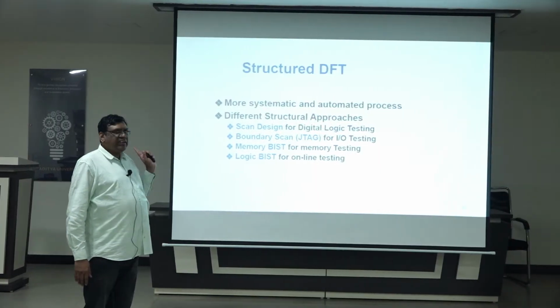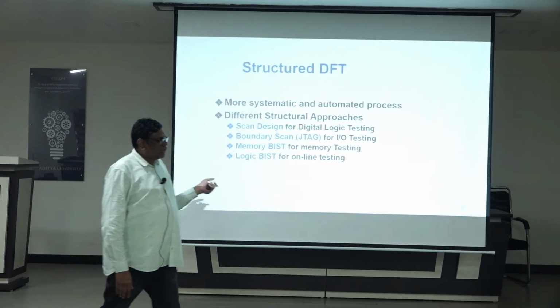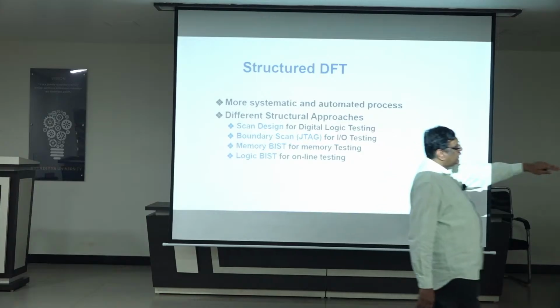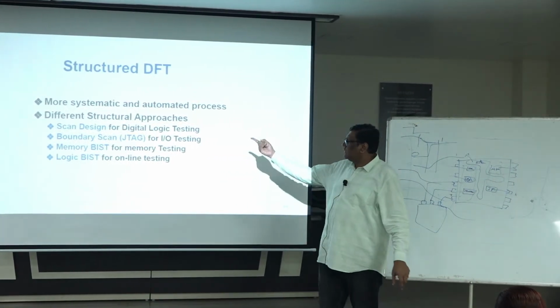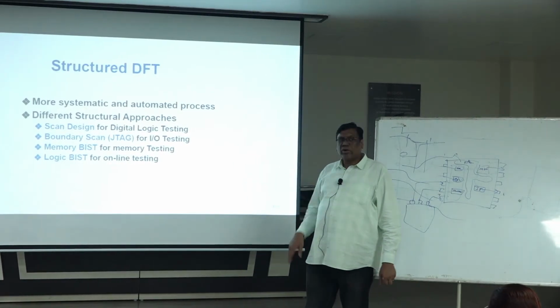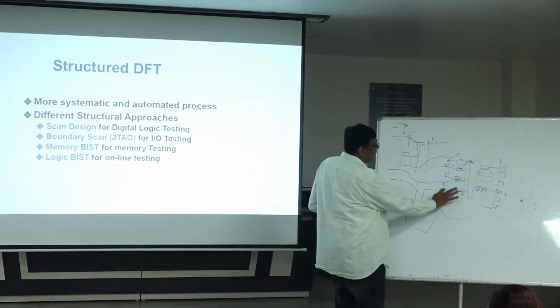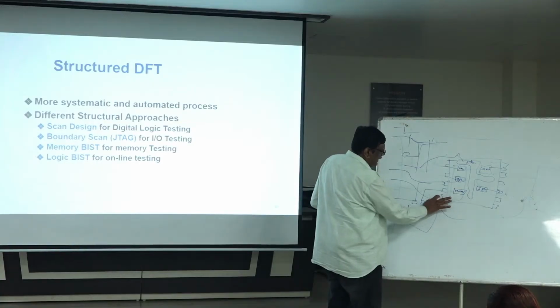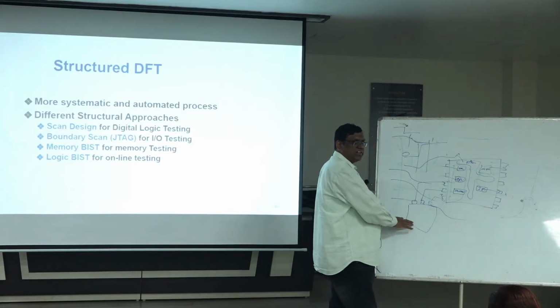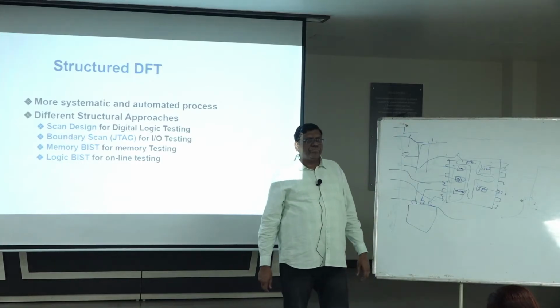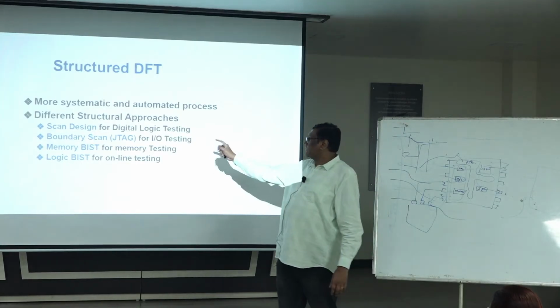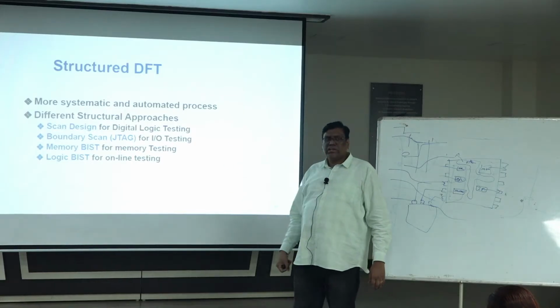So these are the different techniques we will be using. One is the scan design, which is especially used to test the glue logic, the register transfer logic that is there inside, which can be tested using the first technique. The other one is boundary scan, which is used to test all the IO pins and pin to pin connections between different ICs. IC to IC connectivity they will be verifying. That boundary scan we popularly call JTAG.